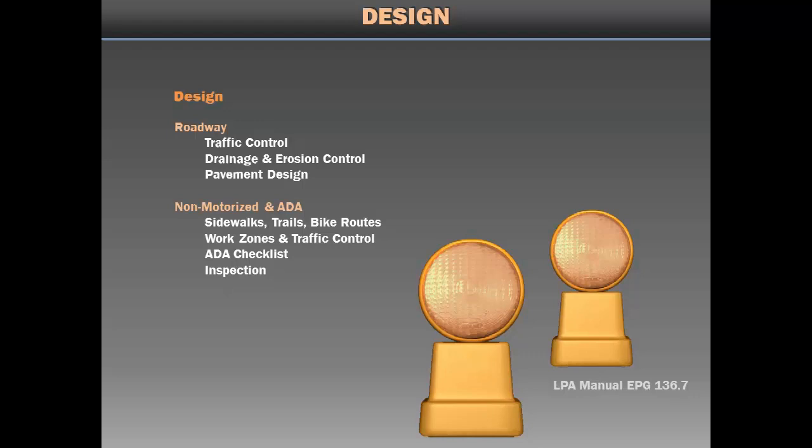Traffic control in general cannot be lump sum. Federal law requires a base set of traffic control plans with specific quantities for each major item. Projects with lane drops that have a defined number of channelizers and signs can be set up as lump sum, but any significant items like concrete barrier, changeable message signs, or arrow panels would need to have separate individual pay items. Projects with lump sum traffic control can create uncertainty and risk for bidders, which may result in higher bids. They can also lead to disagreements during construction.